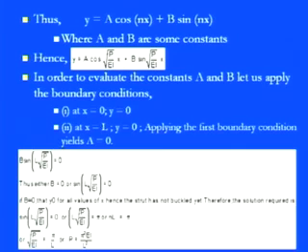And we can say that either B equals 0 or sin(L times square root of P over EI) equals 0. If B equals 0, then obviously y is 0, which is the initial condition, and the strut will not be buckled yet. Therefore the solution required is that sin(L times square root of P over EI) equals 0.